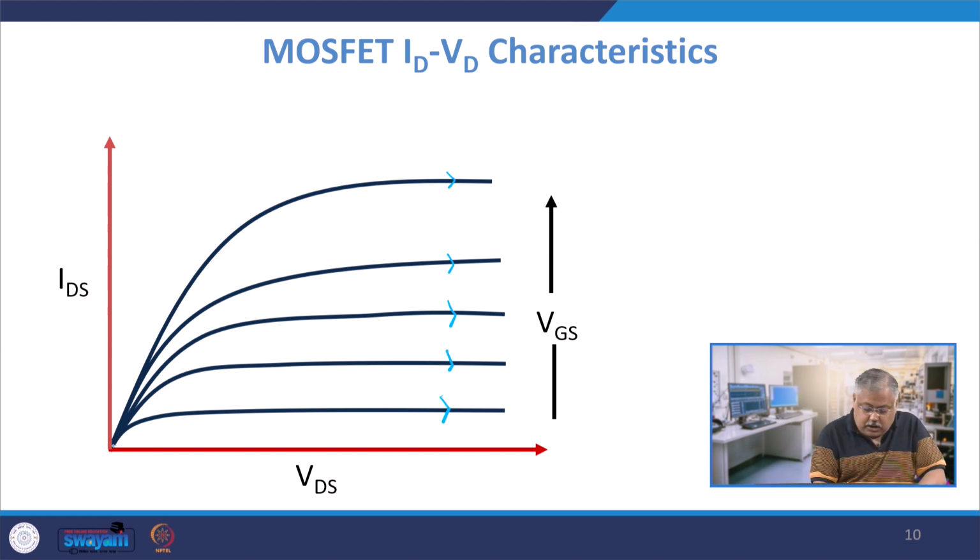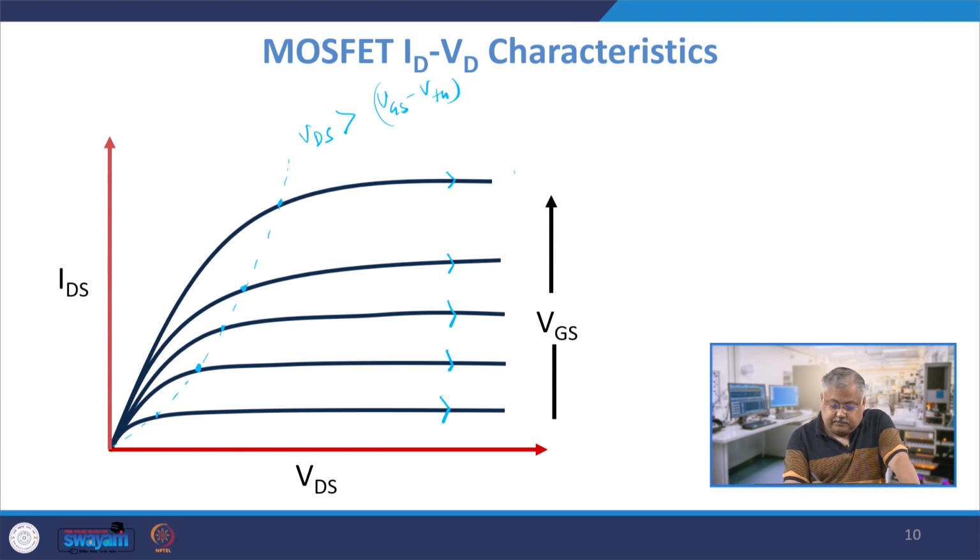So, if you plot a profile here, these values are basically those points where Vds is exceeding Vgs minus Vth. To give you an example, let us suppose this Vgs is 0.5 volts, threshold voltage Vth is say 0.2, right. So, Vgs minus Vth happens to be equal to 0.3. So, whenever my Vds exceeds 0.3 volts, I enter into saturation. Am I correct?